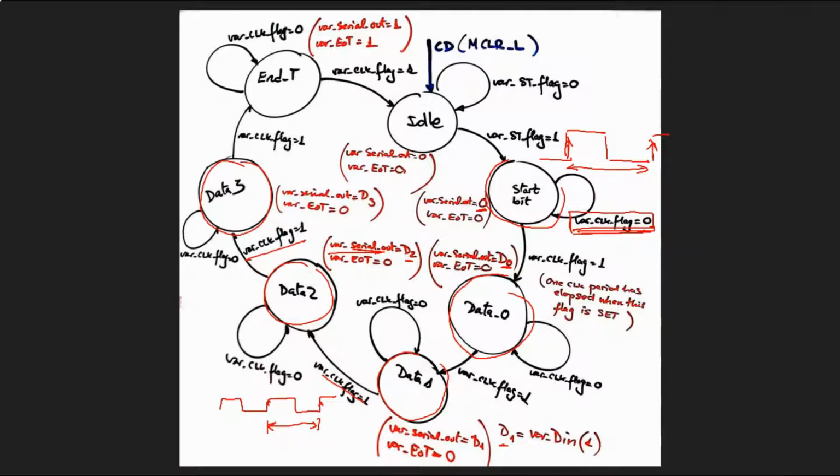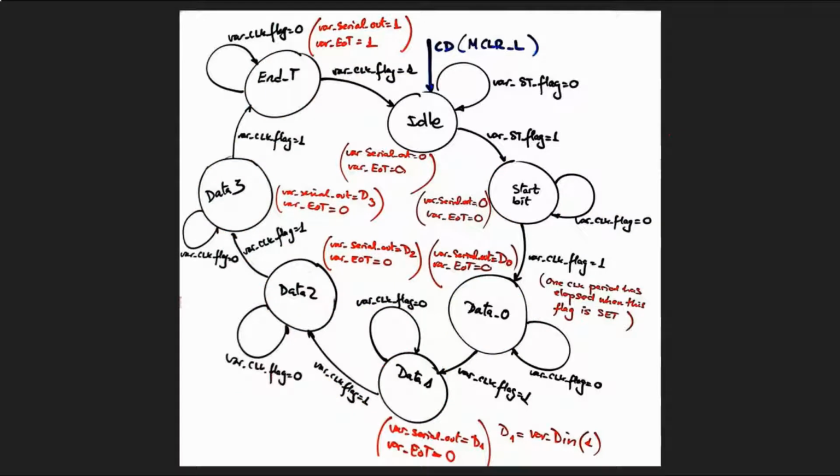And then there is left here an end of transmission pulse that you can generate. In this state, like a kind of terminal count, you are indicating that you are finalizing the sequence. So in this state, you will stay again the same time, one full clock period, just because you like to send this end of transmission pulse. So that's it, the typical and standard state diagram that now, instead of being solved by hardware, is solved by software variables. That is what we have in mind.